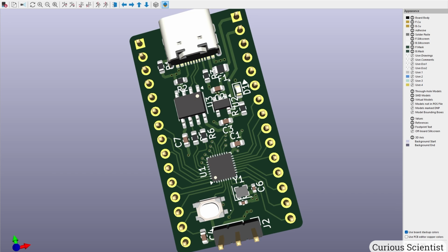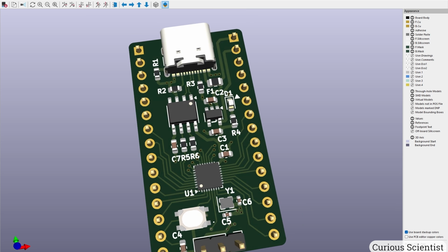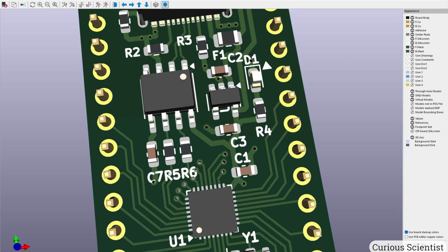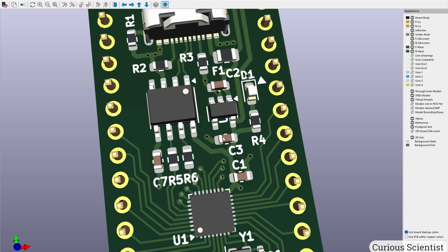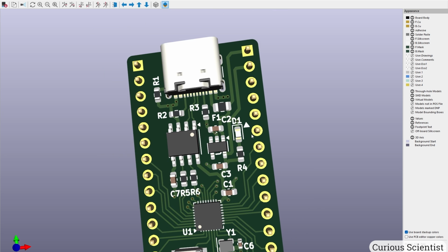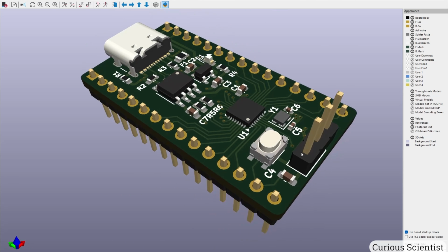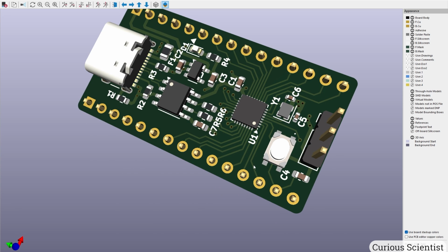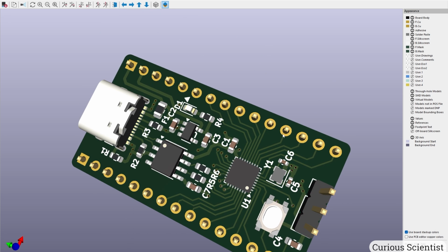So I will just change their size and orientation and lay them out more or less nicely on the board, so we can then assemble the board ourselves. So now it looks a bit more acceptable. Of course, some of the text is cut by the vias, as you can see, but still it's recognizable. Or if you really want, you can move C7 here, R6 here, and you can do further adjustments, but we have to keep in mind that we have to name the pins here so we know which pin is which. So therefore I try to keep this line here and here empty.